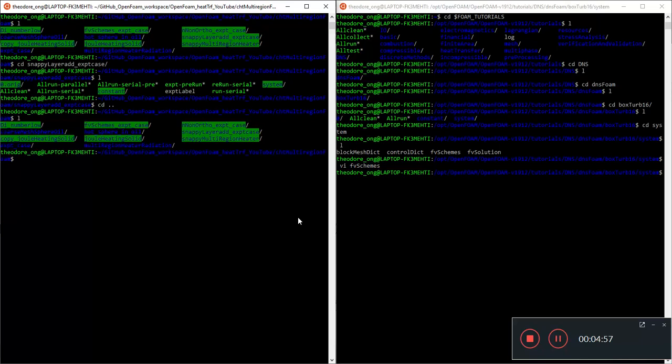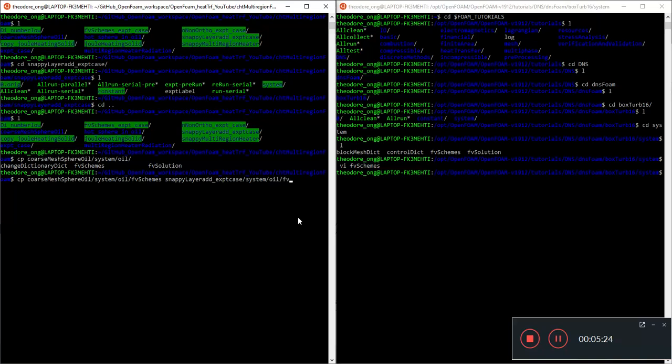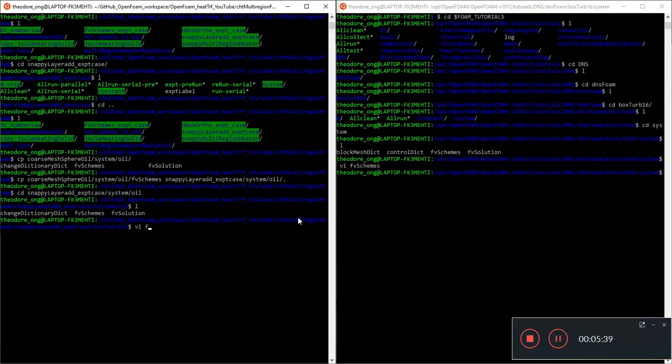First things first, I would like to copy the fvSchemes from my coarse mesh, system, oil, fvSchemes, into the snappy layer addition system, oil, fvSchemes. I'm going to put it there.